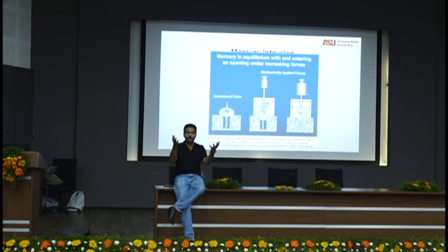for example, if you're building concrete columns, you will never see a compressive failure of a concrete column because you have confining steel also. You will see spalling, you will see deterioration, you will see chipping off. That's all because of bad concrete and environmental processes, not because of the compressive load that is happening. Okay? So, thing to remember, compression should not cause failure.